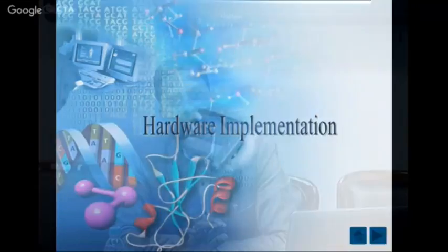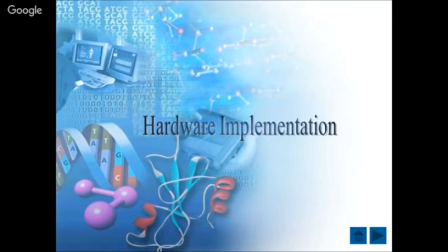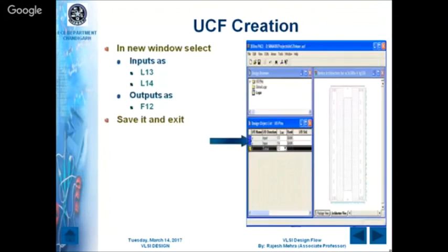You can't analyze the output if it is in the form of zeros and ones. It is going to be just 16 waveforms with 0 and 1 transitions, and it is very difficult to analyze whether it is a low pass filter or not. It can be done with System Generator with hardware co-simulation. So in this way,